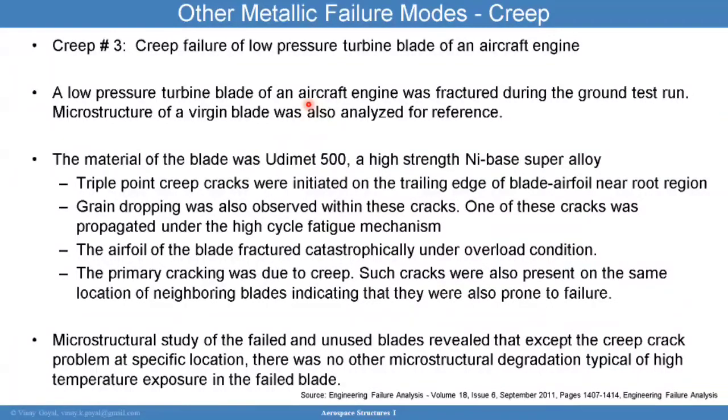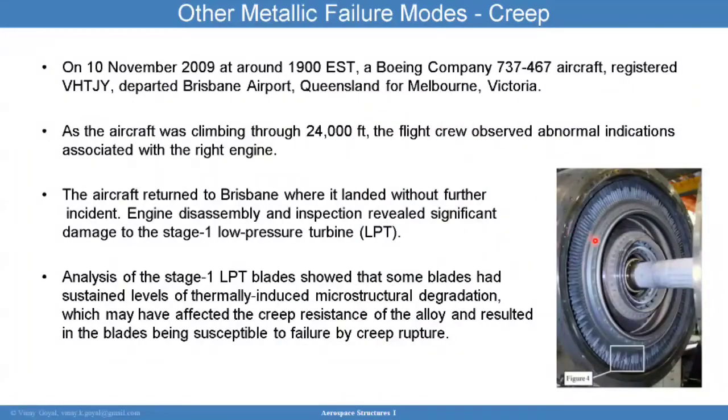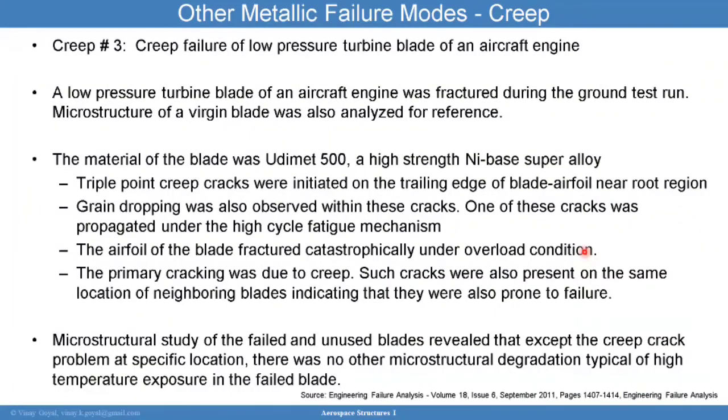Now, I want to keep in mind and explain to you that blade airfoil designs, in this region where the blade attaches to that ring, tend to be areas of high stress because of the centrifugal forces and also the thermal behavior and gradients across these systems. And so that produces a sustained loading condition that's perfect for a creep mechanism to set in.